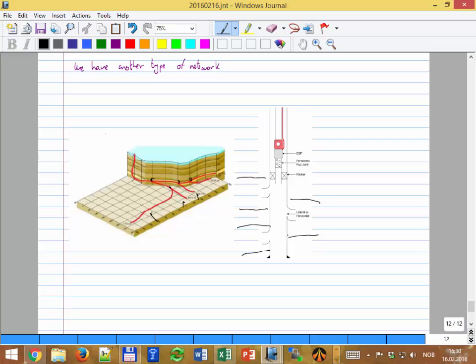Also, with the case with networks, remember that I told you that it's not only the productivity of the layer, but also the distance that it has, because everything counts, okay? It's like the resistance that the well has from the formation all the way to the processing facilities. If the pipeline is too long, the diameter is too small, or if it has, for example, accumulation of solids, then it's causing an extra back pressure. So everything matters in that case. And also in the formations the same, okay?